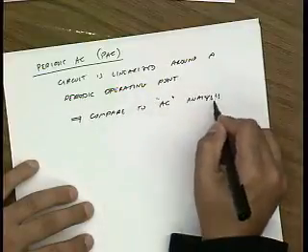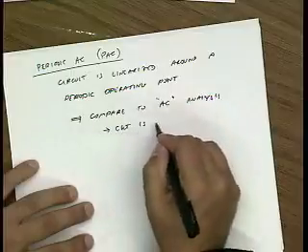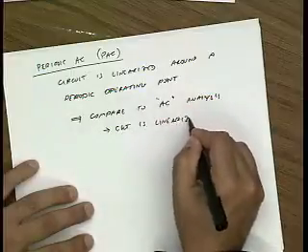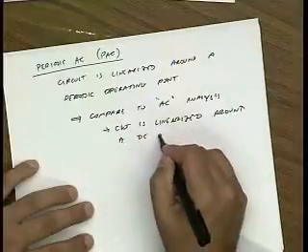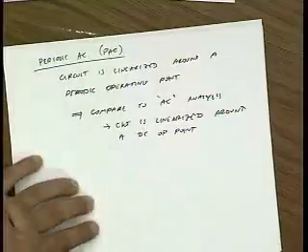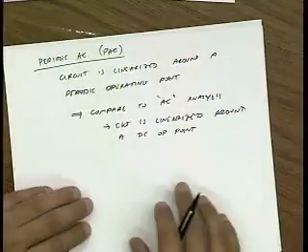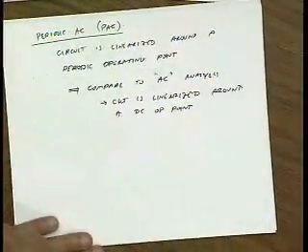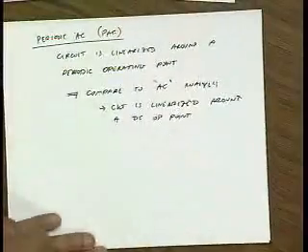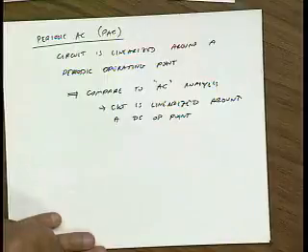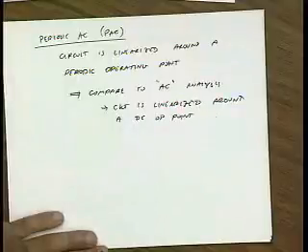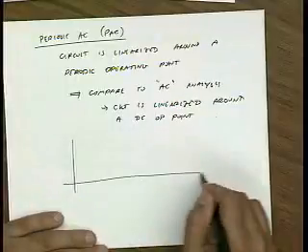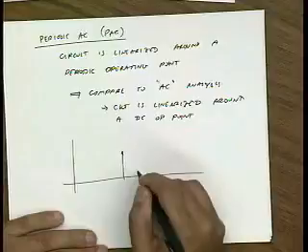In AC, the circuit is linearized around a DC operating point. Now, what's complicated about PAC is, what does a transfer function mean, right? In fact, you can see that in periodic AC there are as many transfer functions as there are harmonics in your signal, right? Again, a simple mixer is a great example to see that.